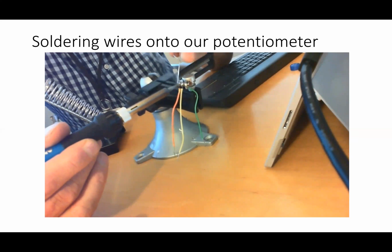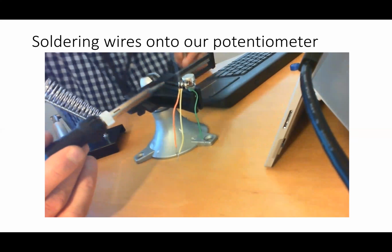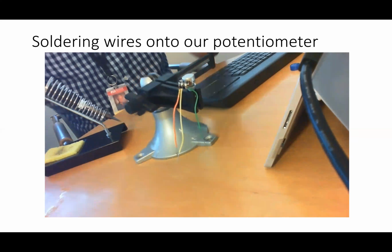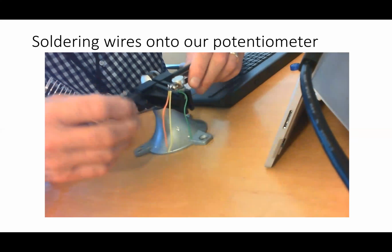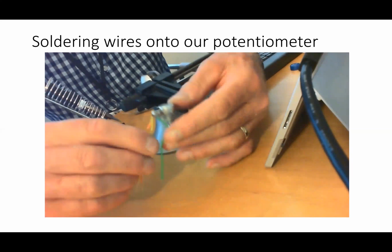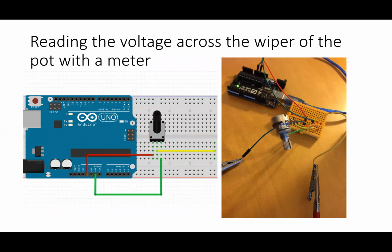And when it's hot enough, it'll flow beautifully and freely and form a smooth connection, which when the solder solidifies, will then rigidly hold the wire onto the potentiometer, and you can see now they are rigidly connected. All right, now we've put some wires onto our potentiometer.